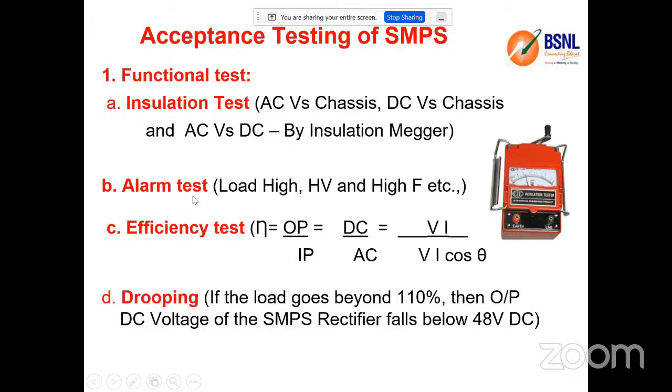Then they verify the alarm test, whether the under voltages, over voltages, over current, high frequencies, module failures, or any temperature variations are detected. All these things are verified with the help of the alarm test.